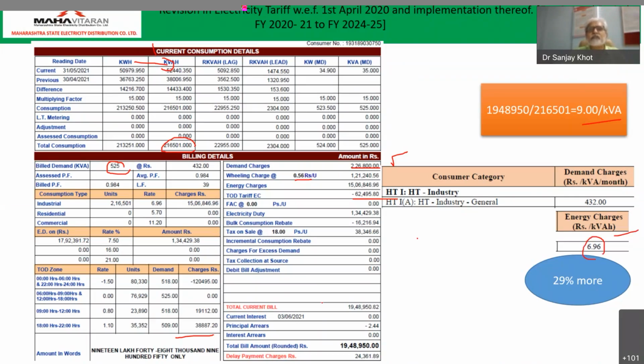Now the next step is, during the audit, to conduct a detailed trial test for selected equipment, because for some appliances we need to conduct trials for 24 hours also. Suppose a compressor is there, a boiler is there, air conditioning appliances are there. There we need to understand for what period we want to take the trial or the readings.